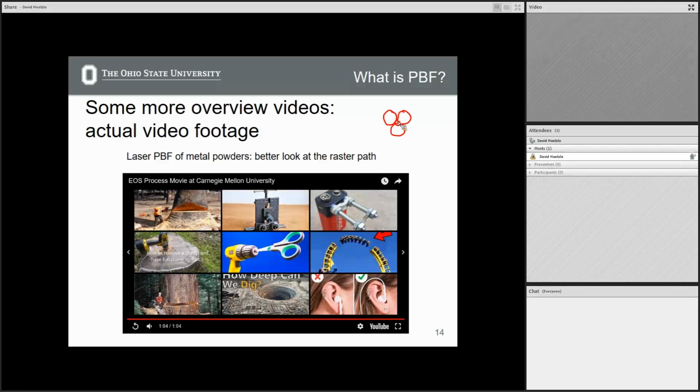So at every layer, they fuse the metal and it shrinks. Whatever the powder height was, somewhere around 50 microns, is now going to shrink to around 20 microns. But when they pass the recoater blade above, that's going to fill in that gap at every layer, because you can put powder on top of that. Does that make sense?